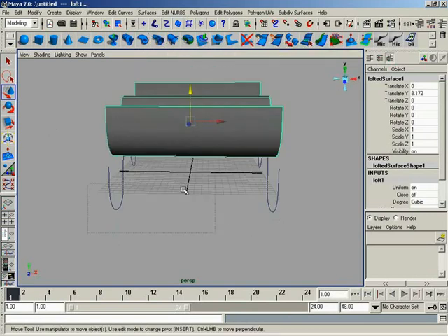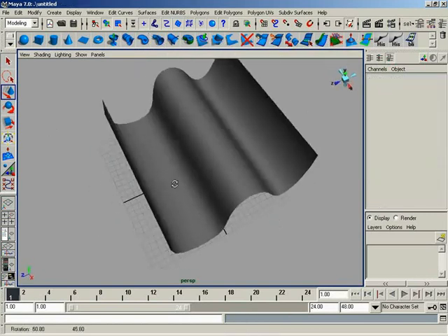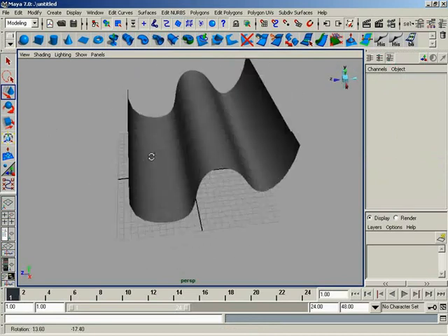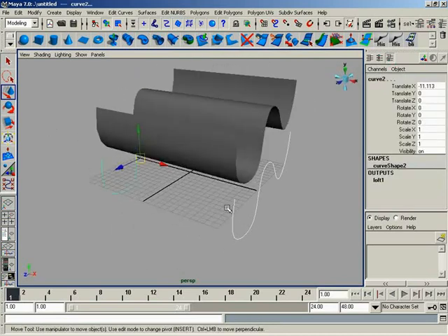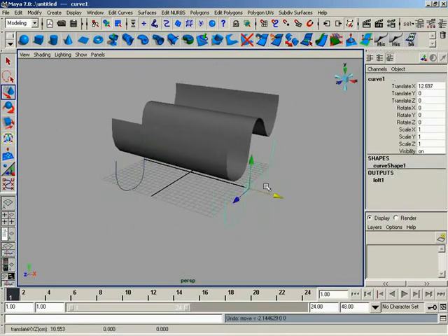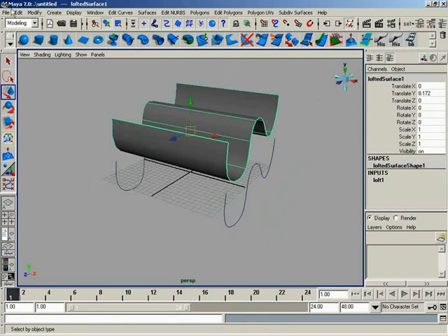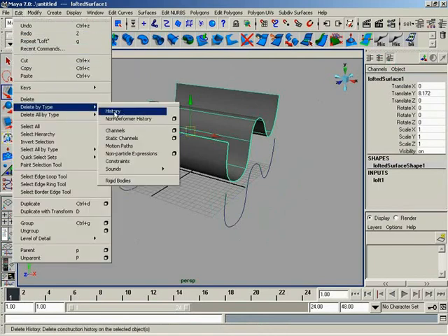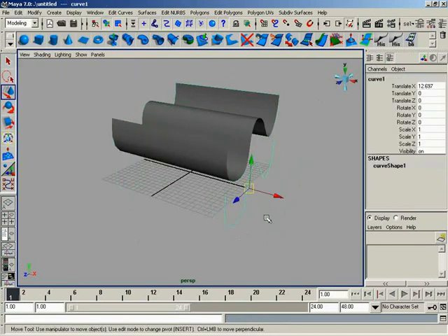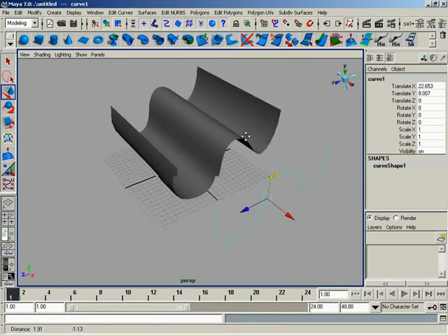And with that, let's go ahead and grab our two curves. We'll nuke those out. We now have a beautiful NURBS surface. In fact, hang on, let me hit undo. Let's leave one of these curves in place. Let me delete history off this guy, so Edit, Delete by Type, History, and I'll delete out one curve. We'll leave the other one here, just so that everybody can see. We have a NURBS curve and a NURBS surface.